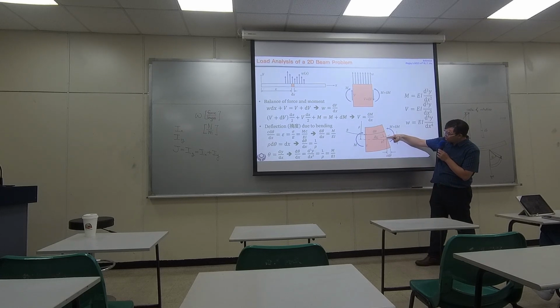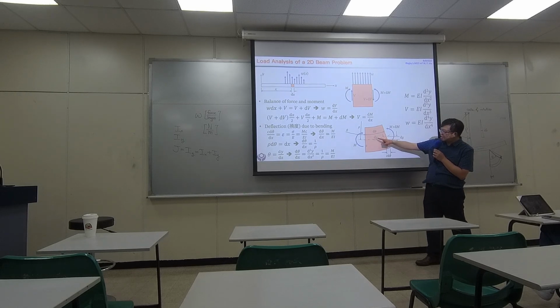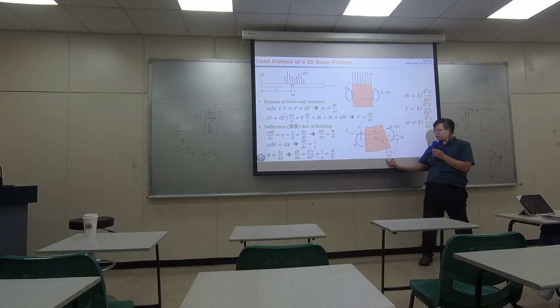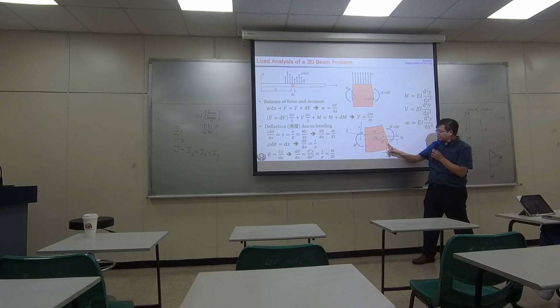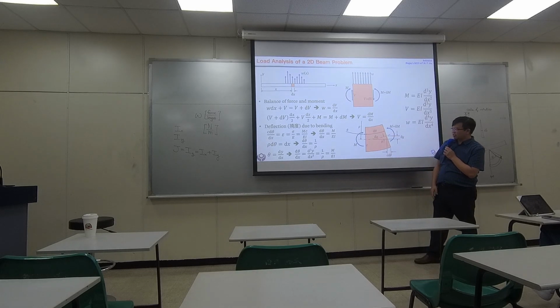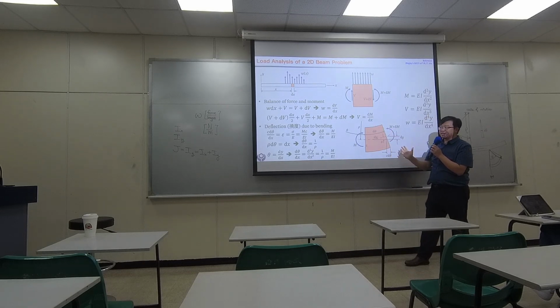We can use the radius times the angle right here. This angle is the same as d theta. The radius right here is c. That's why this increment is almost the same as the arc length right here. So it's c times d theta, the same angle here and here, due to symmetry. So this increment c d theta is actually the increment of the bottom edge after bending.